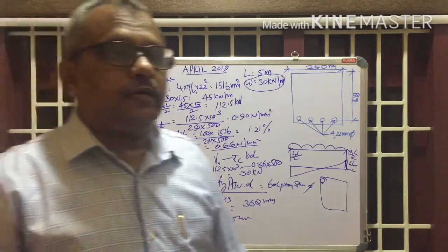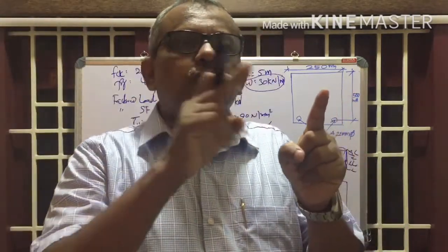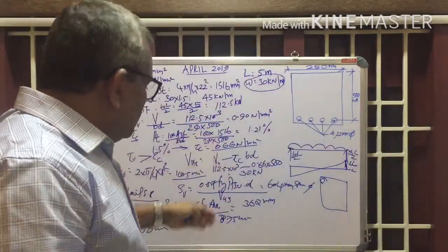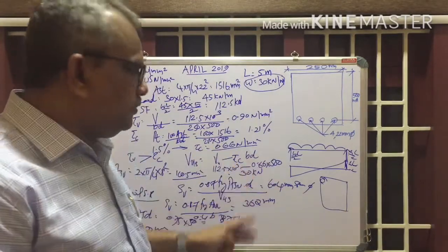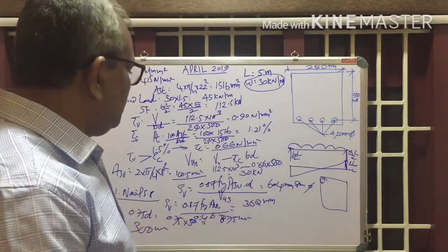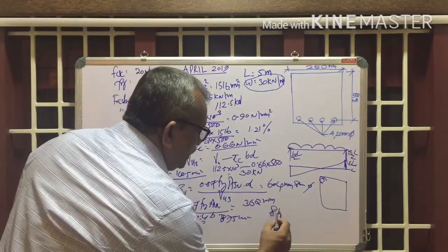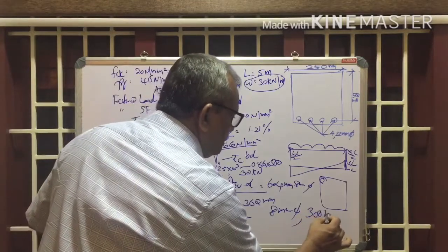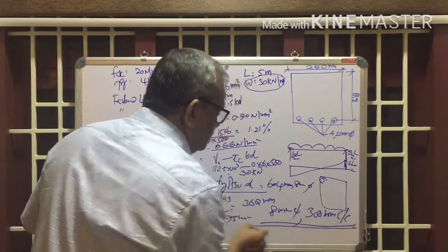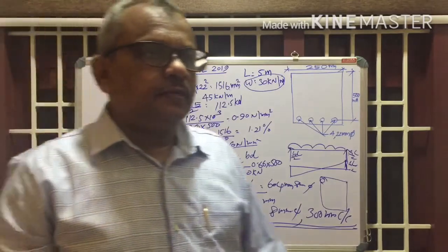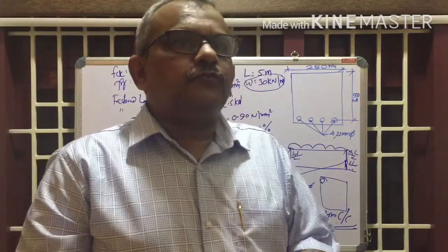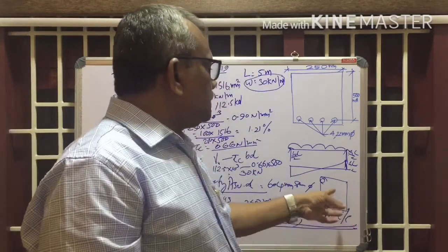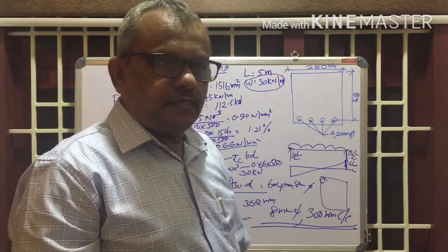As per the code, the spacing of the bar should not be more than 300 mm. So out of these, when we check all the provisions from the code for the spacing of reinforcement, the minimum is equal to 300 mm. Therefore, provide 8 mm dia two-legged stirrups at 300 mm center to center. So that is the design. We have to provide shear reinforcement of 8 mm dia two-legged stirrups at 300 mm center to center, right?